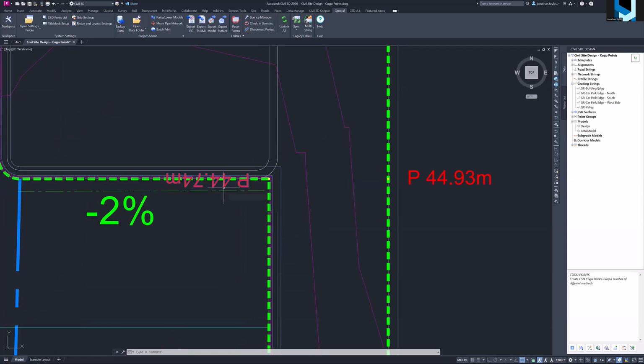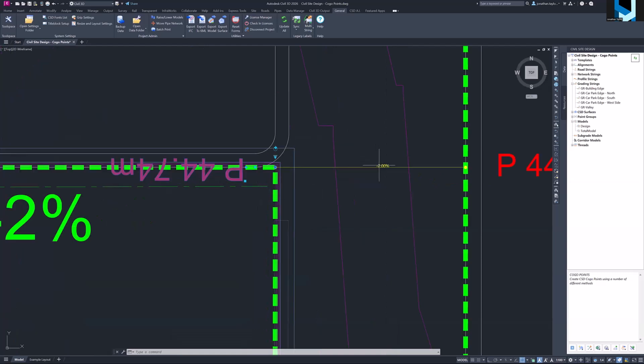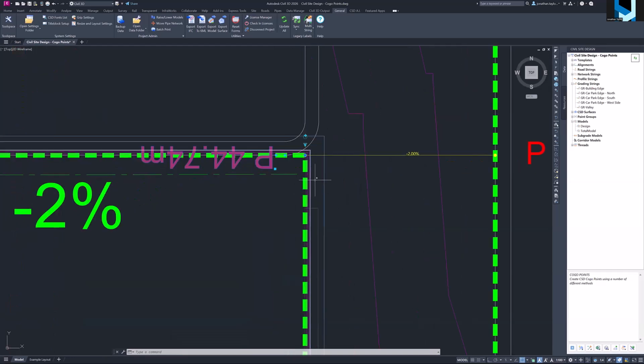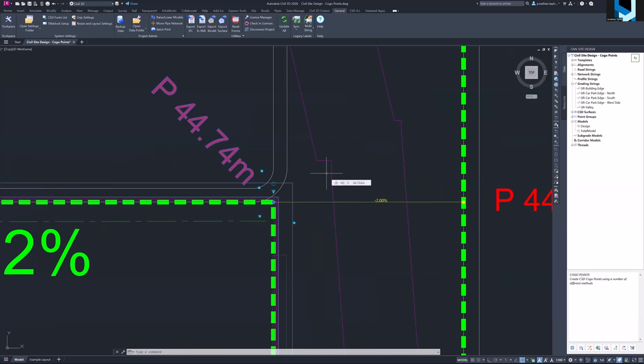Now, this Cogo point, if we left click on it, will yield grips. Also, if you've put a slope in there, even if you put 0.000001, that little yellow marker appears, which is great because it tells me it's connected to that Cogo. The grips are great because you can use them in BricsCAD. So you remember that 45-degree increment I added? That's why I've added it. You could manually just twist it round if you're not going to adopt that 45-degree version, which you don't have to. But I'm going to pop this here. Obviously, I can flip them. I might flip it, have it there. So BricsCAD users, you can use it.